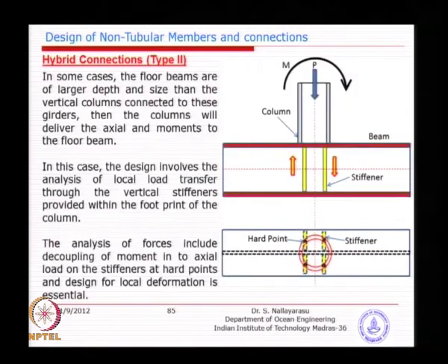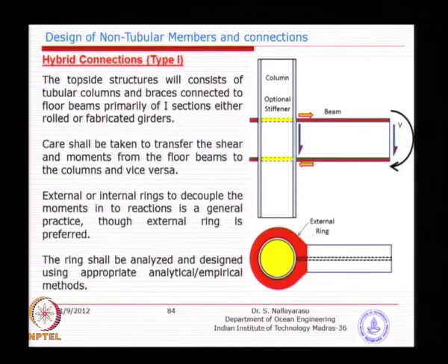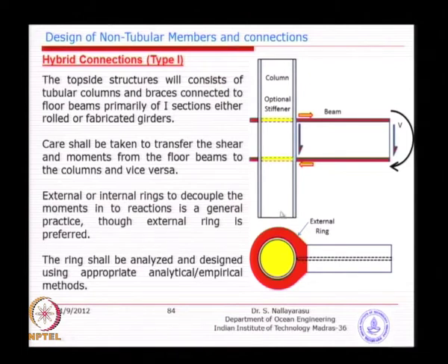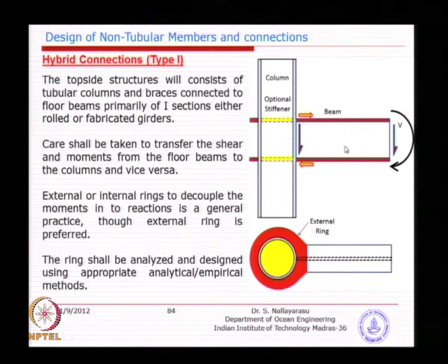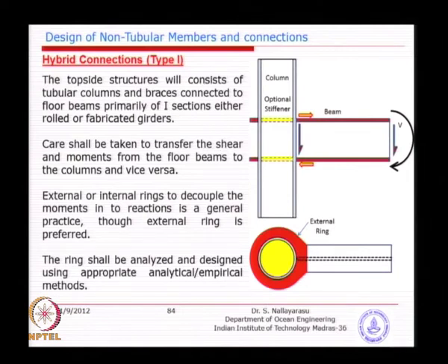You will see that all three of them have a little bit of difficulty in designing, especially the first one. You see here you have a column and we have an I beam coming in; it is not easy to connect. What we need is basically to avoid local buckling of the pipe, because the loads are going to come so concentrated. When you apply a moment, what happens? Such an axial force will make pulling of the tube across the section, which I think we were looking at during our tubular connection design.